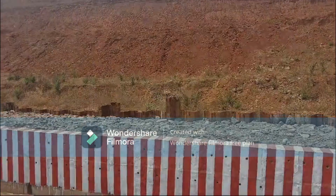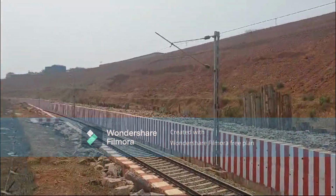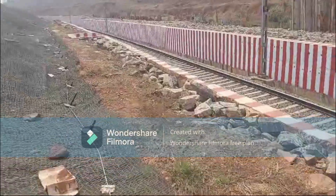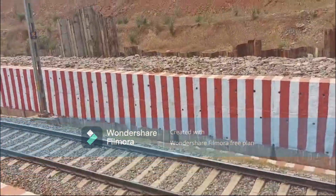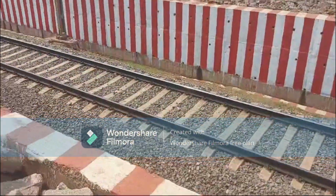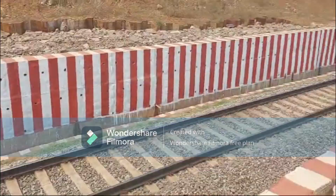Here it is guided to retain the earth pressure, and then this line was constructed, because the line level is very low, from the ground level. So at first they provided sheet piles, and then excavated, and then constructed this type of retaining wall.